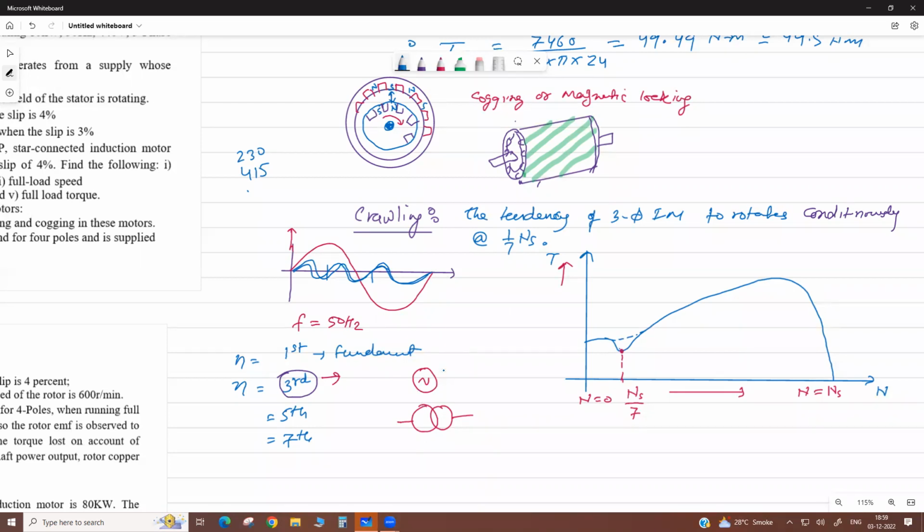Now, this alternator is connected through a transformer, then we get a step up, step down. But here, if it is a delta star, then your harmonics circulate within the delta. They do not come outside to the load side. In delta connected or delta star like that.